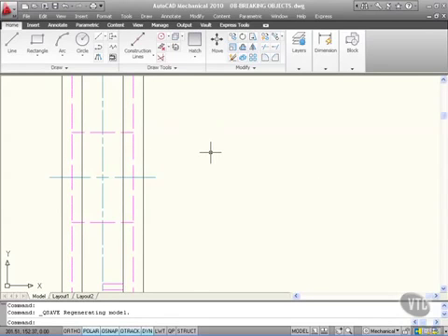Now, they're hidden detail lines. And what they're showing is the indent on the outer edge of the belt wheel. Now, there is actually a hole for the central shaft to go through, but at the moment it's blocked. And we need to break this line here and this line here between the intersection there, intersection there, intersection there, and intersection there. Now, you could just use trim, but I want to show you how to use break. Trim would work just as well. Again, 2, 3, maybe 4 ways to skin a cat when you use AutoCAD.